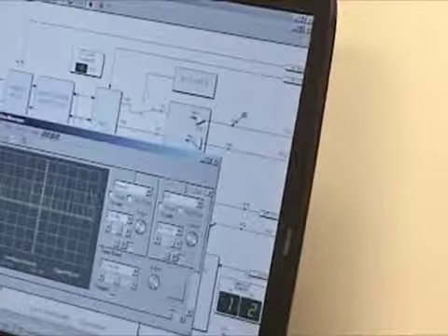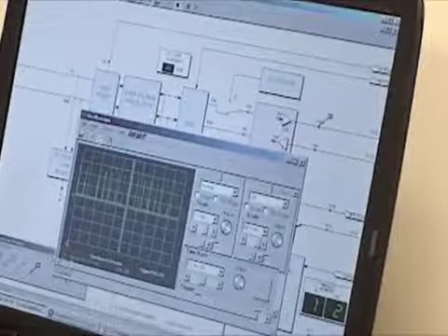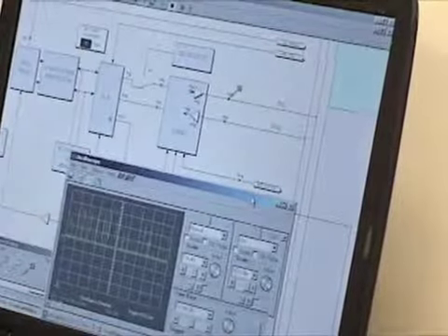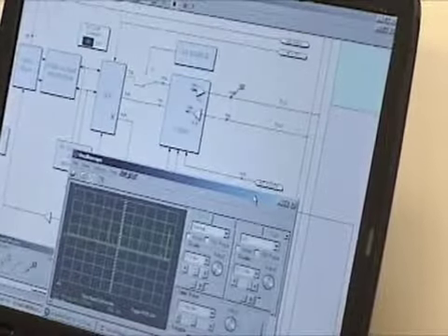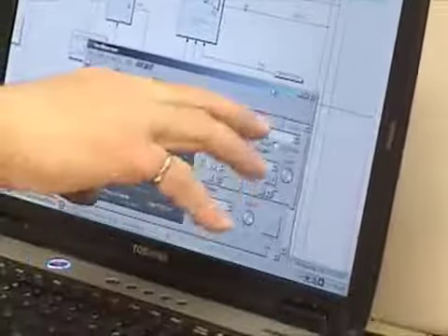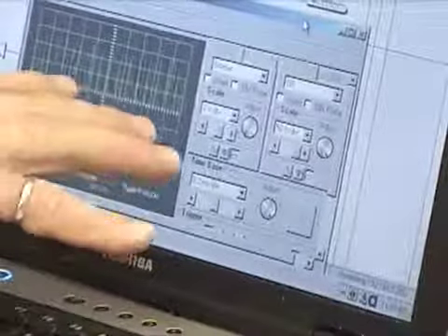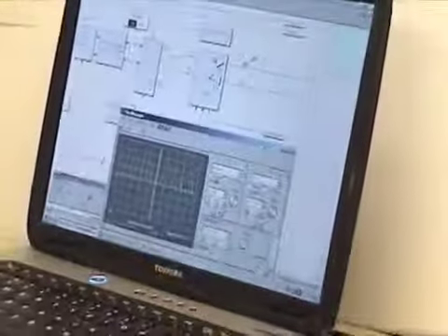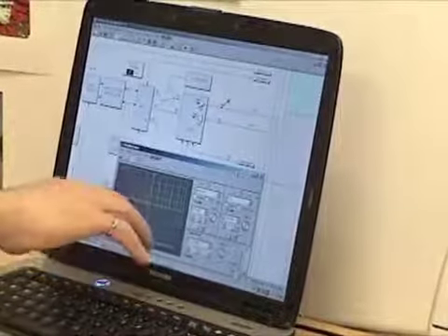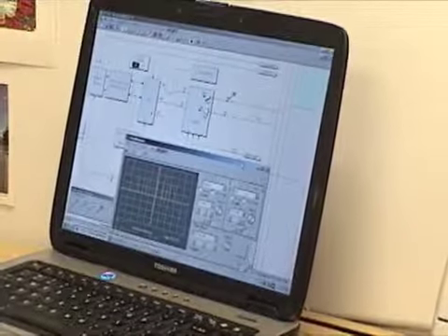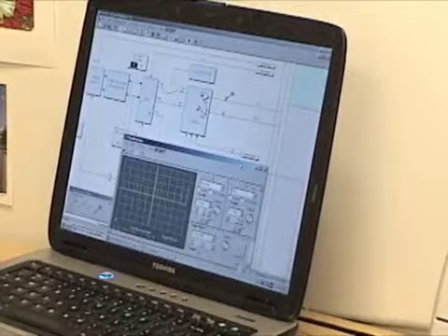Alright, now if we wanted to, we could also show that you could have several telephone conversations going on, several telephones interfaced to this box. They're all producing their own PCM codes, and then you can show how all these codes are added in different time slots, and they make up the complete picture of the PCM leaving the central office switch. It's multiplexed into a T1 signal where you can have 24 channels doing that. So that's basically it.